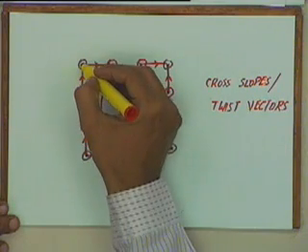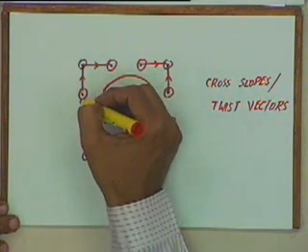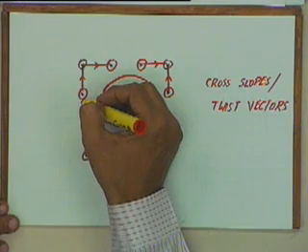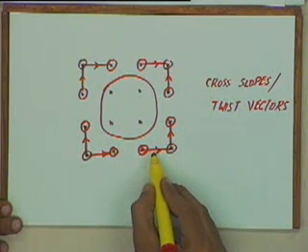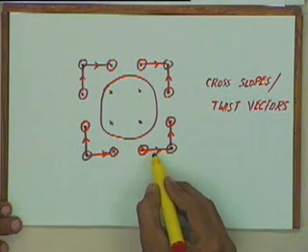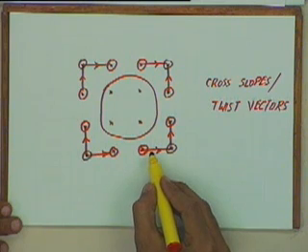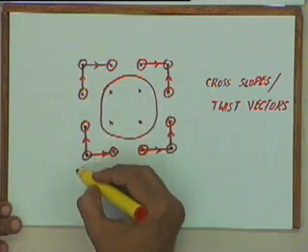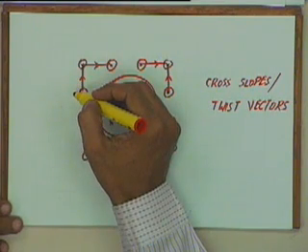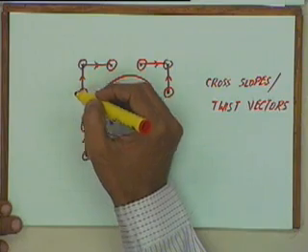Similarly, at this point the tangent vectors are controlled only by 3 points, and we can extend that to a general surface of degree n. If we have a surface of degree n, if I consider k points in this direction, the kth derivative will be controlled by only those k points. Similarly, k points in this direction will control the kth derivative in that direction, and so on. That is a property which is specific to Bezier curves and Bezier surfaces.